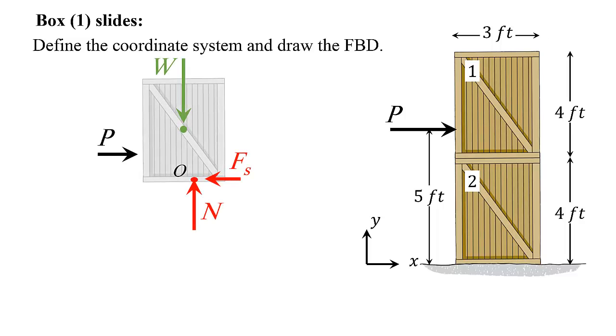All I need to do now is apply the equilibrium equations. Since there is sliding, the point O where the normal force acts doesn't have to be at the end. Applying the summation of the forces, I can solve for P, which will equal Fs, which will equal N mu12.